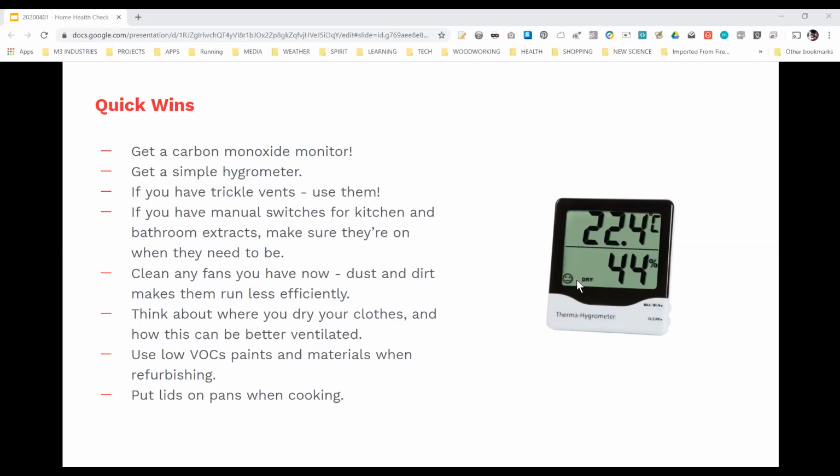Yeah. The thing about the diagram about how condensation works, I slightly disagree with the primary statement that was made that it's moisture in the air that causes condensation. I'd actually expand that to say that it's the combination of moisture in the air, cold surfaces, and not enough ventilation. And it's about improving two or more of those, at least a bit, so you can get rid of the condensation. Insulation or fabric first can't be overemphasized as a way of reducing energy and reducing carbon in the country, and that immediately warms the surface up because you haven't got a heat flow through it. So I definitely favor that.